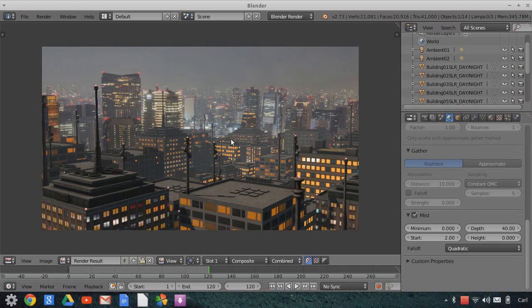One of the features is a depth of field, so that you could perhaps get depth of field into your shot so that the foreground buildings are a little out of focus and the far background buildings are out of focus, and then you have just a plane of sight that's in focus to add a little bit more realism. Also, you could do some frame interpolation or oversample your animation to add some motion blur.